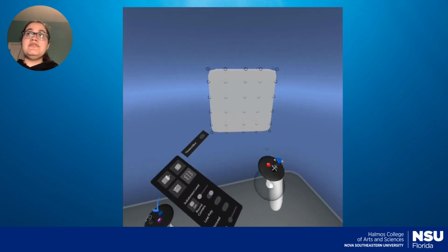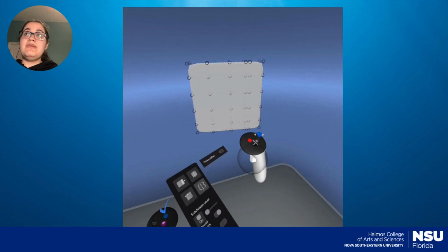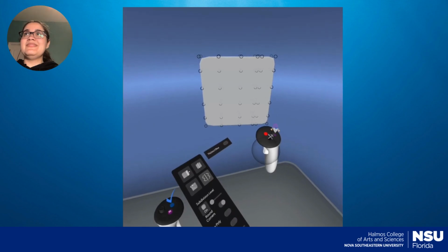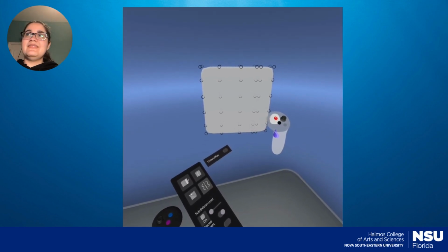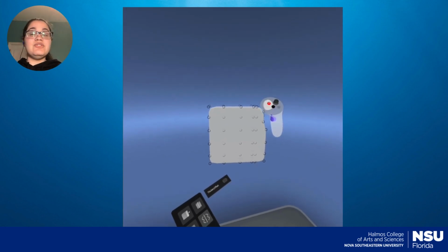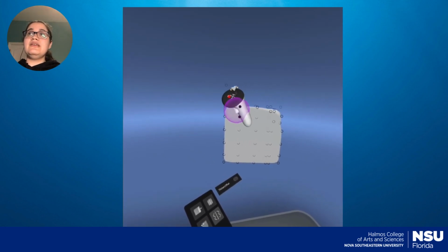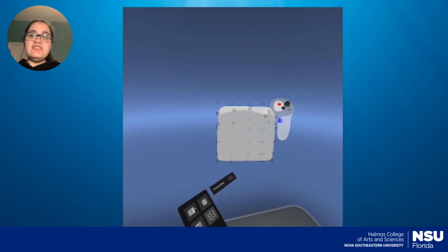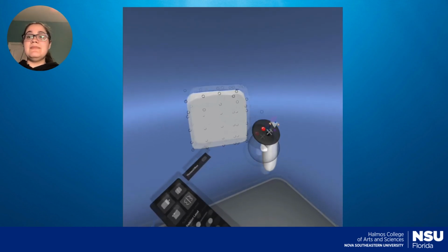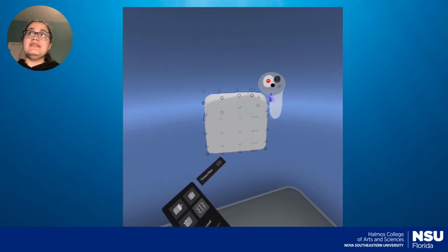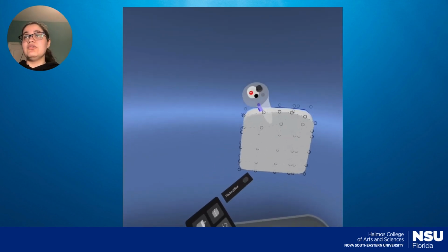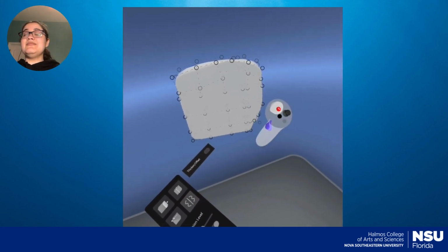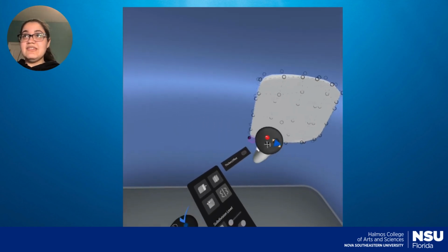And then by pressing subdivision on, you basically round out the shape to make it less geometrical, sorry. And with that inner button again, which is very crucial for anything with 3D modeling, you could basically mush the points together. You can also change the size of this grasp, as I said previously, by wiggling the controller up and down. You can make it bigger or smaller, so you can grab as many points as you would like all at once. Relatively, my experience with this is probably the most advanced part about Gravity Sketch.